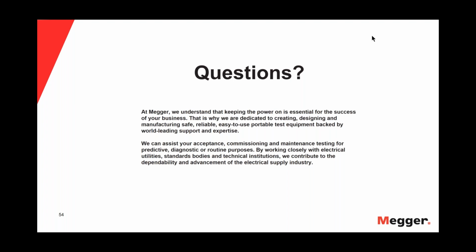I did something similar on a low voltage cable, a 4-conductor cable on a street light, and when it rained, the street light would go out. And when it dried up, the street light came on again. So it was not a true cable fault, but it was a condition where you create a lot of leakage with moisture.